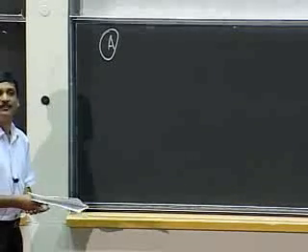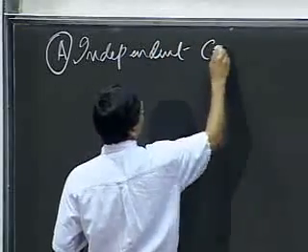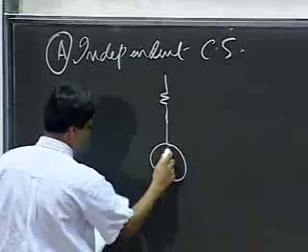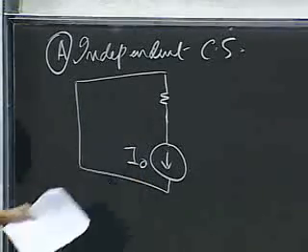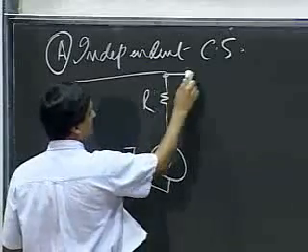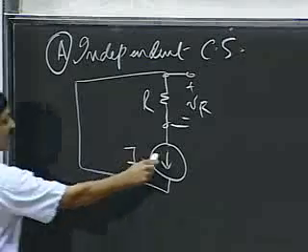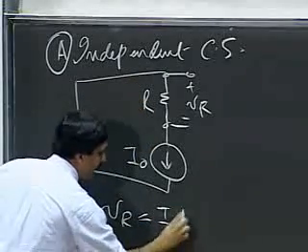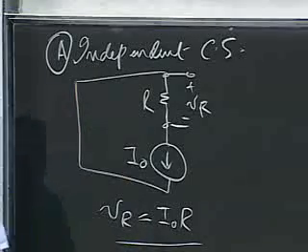To begin, just so you can build up your intuition, let me start by doing a very simple circuit involving an independent current source, just so we can relate back to what we've been doing so far. So let's say I have some resistor, and I have a standard current source with current I0. This is an independent current source. Remember the circle? And some resistor R. And let's say I care about the voltage across the resistor. So I have current I0 flowing through it. So I can very quickly write down VR as simply I0 R. It's the drop across the resistor when a current I0 flows through it. So this is what you've been used to doing.